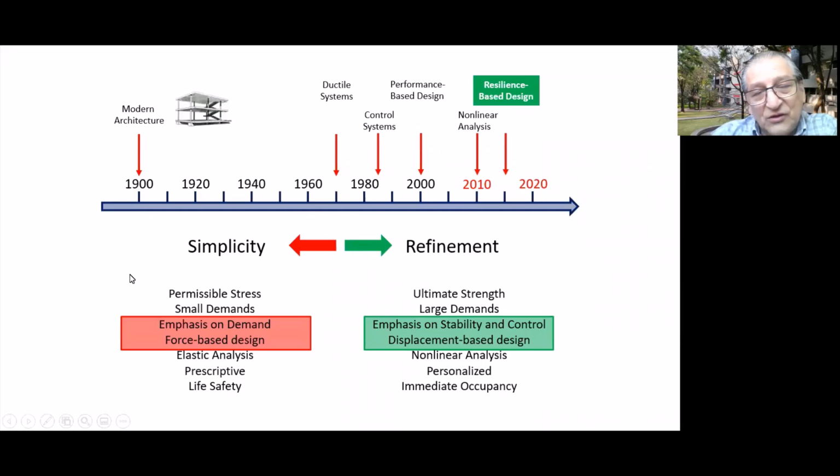So I'm going to concentrate my attention on a big change in which we feel that we should be abandoning the force-based design format and placing more emphasis, not on strength, but on stability and control, and that implies moving into a displacement-based format.